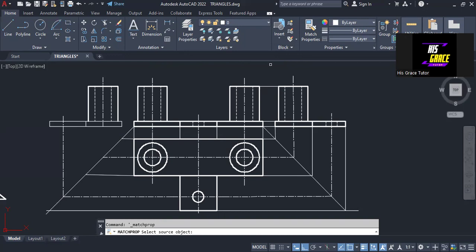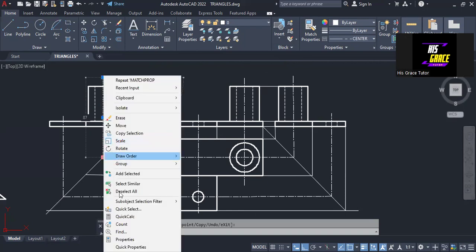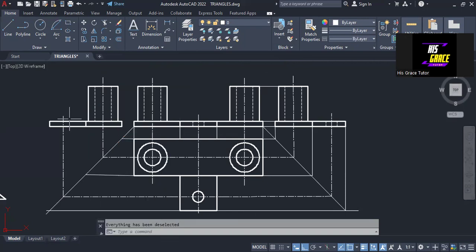All right, so then there's some that we still need to show here. So this line, I'm going to join it with this line. Okay, so we are going to offset this to a distance of 6 to both sides. So we give it a distance of 6, and then we offset it to this side. Okay, so I'm going to trim this one.